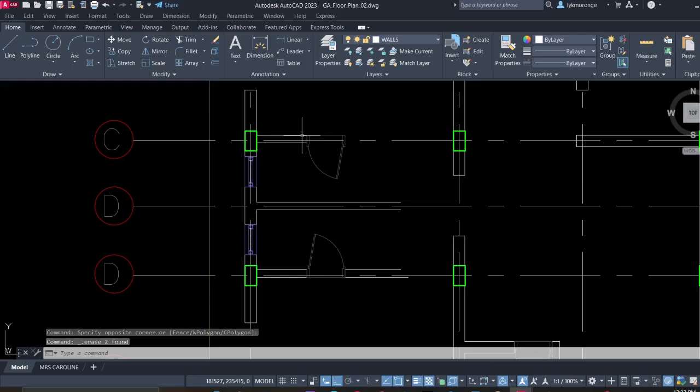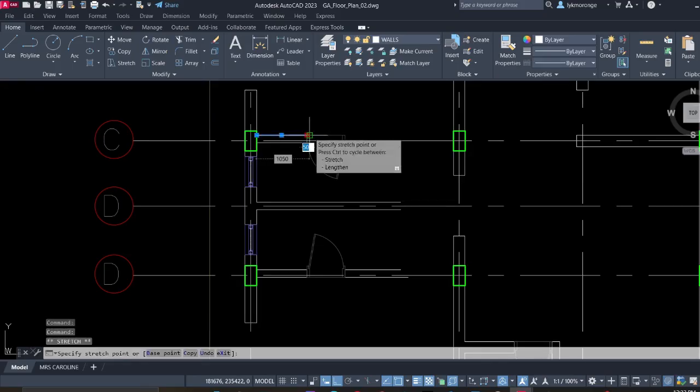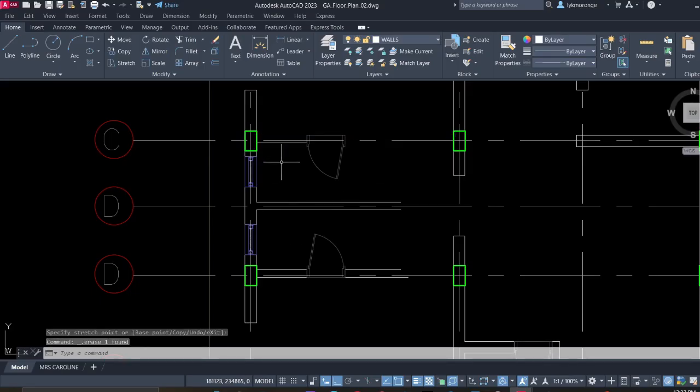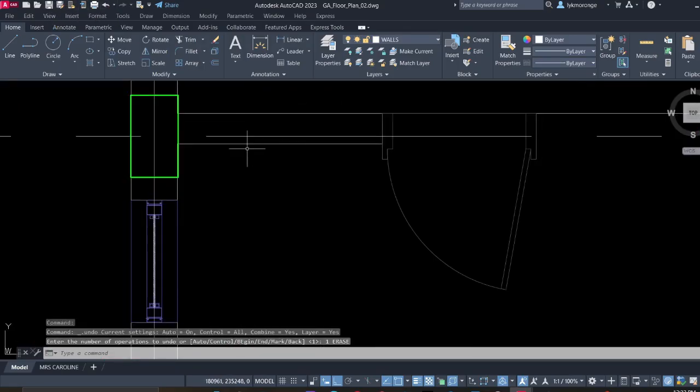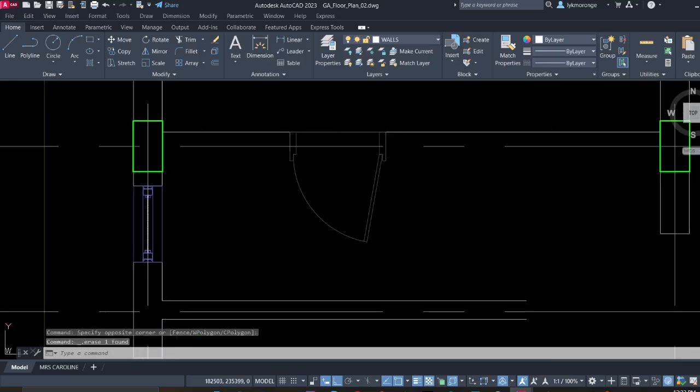So you can simply click on this, right click here, and ensure that the auto mode is on. Just come and fix it there. Undo. So select on this, but now you have to be sure what the depth of your beam is. So just click on this.